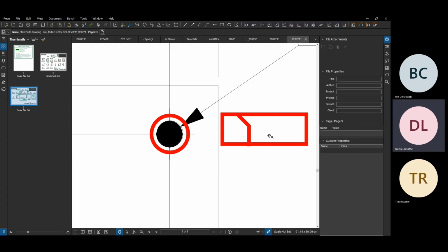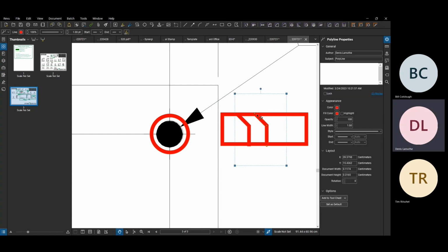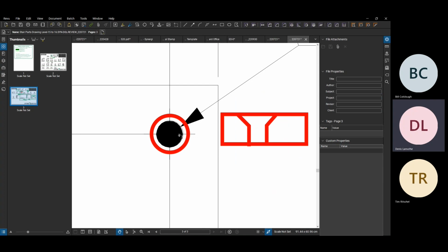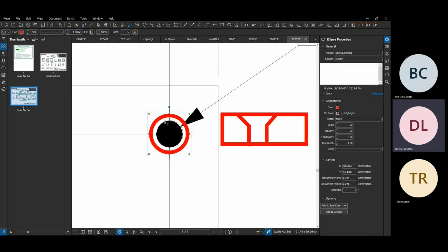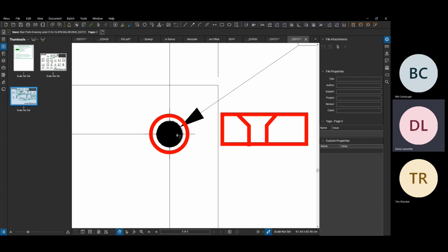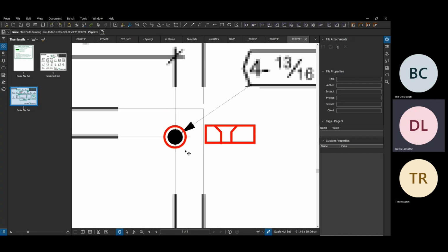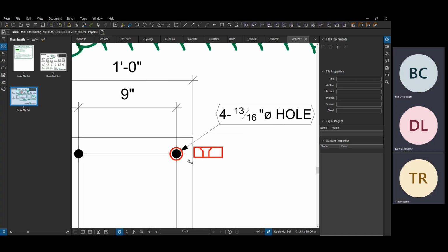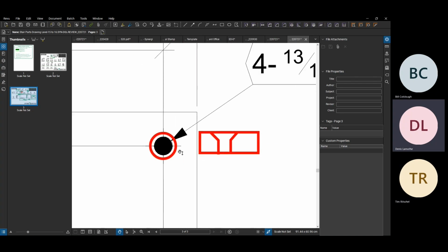You have that there, you have this here. Ideally you should see a circle that represents the outer rim, and then a circle that represents the inner part. So graphically, instead of just relying on a note, they can also visually look at it and say, oh yeah, there's something funky about this hole. It's probably countersunk or counterbored or something.